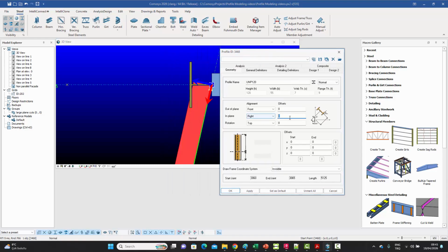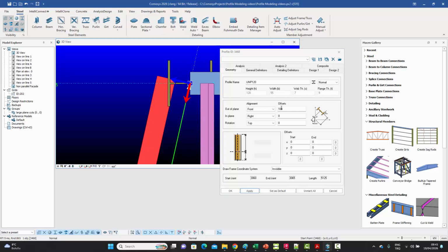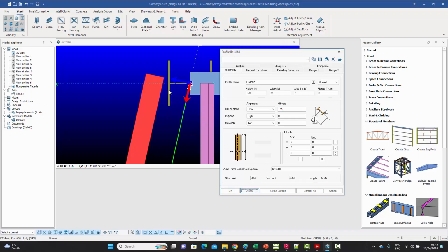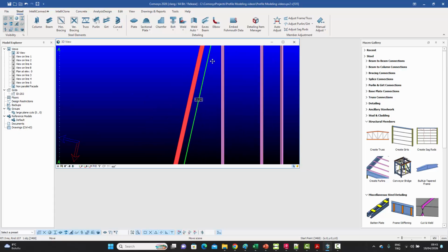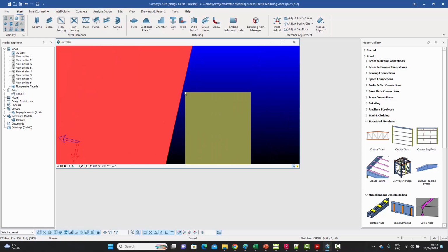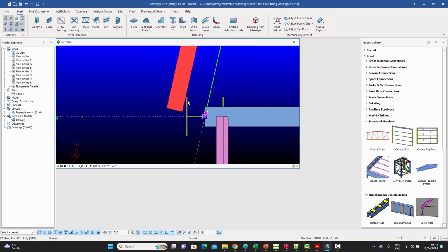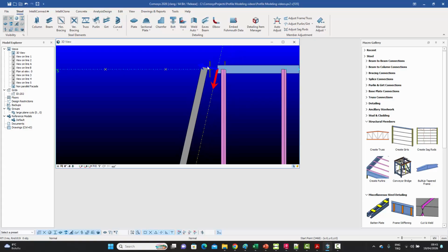Whether it's this one, let's just see. Let's just put a number like that. Oh, this is not the one. Sometimes this needs to be a bit of a trial and error. Yeah, this is the one I'm looking for, the offset I'm looking for, but let's give it a bigger one. Let's try 175. Yeah, this seems to be working. Let's hope it's not clashing with the column at the other end. Yeah, it's just cleared it. That should be enough for me. So an offset of about 175 would work as far as the facade girts on this particular view are concerned.